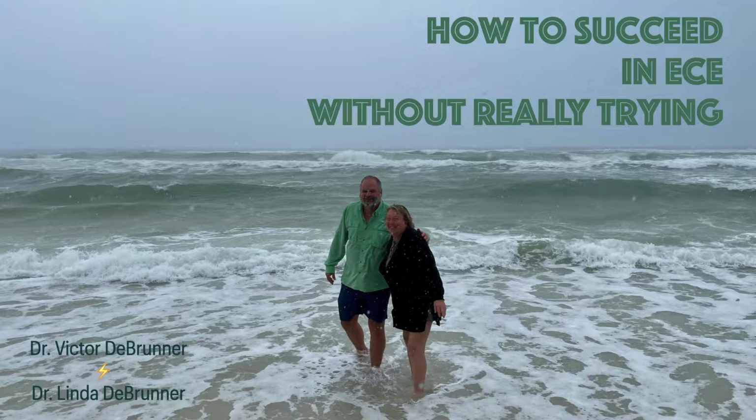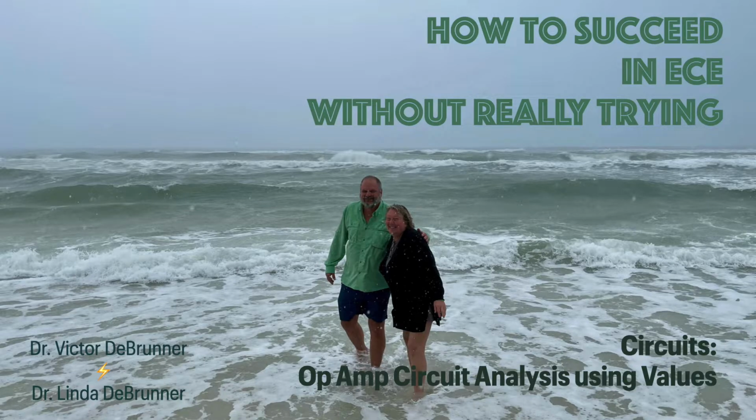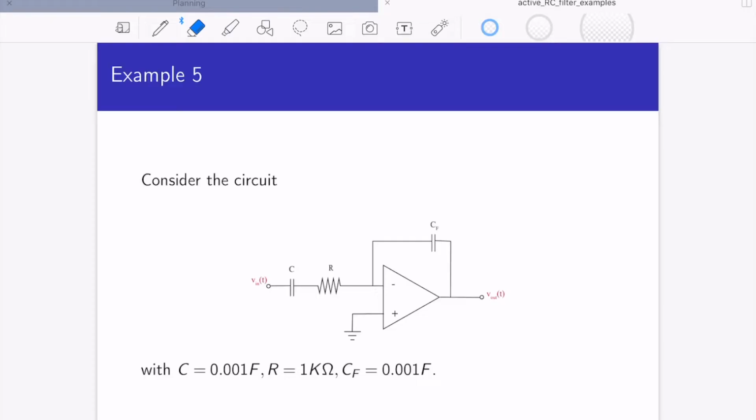I'm Dr. Linda DeBrunner, and here's an op-amp example where I'm doing the analysis using the values of the components plugged in early. Here's a simple circuit, a couple of capacitors and a resistor, and we're going to follow the same procedure we normally follow, right? Which was to remember that IN is equal to 0, so the currents going into each of those terminals are equal to 0. We also know V minus is equal to V plus for negative feedback, which we have.